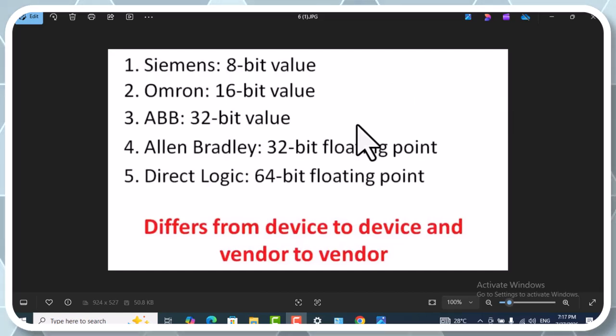And my friends, the OPC server solves this problem, which occurs when you read data from different PLCs or different protocol types. It reads the original device data through the correct industrial protocol, converts it to its own data format and applies it to the OPC protocol, and after that your OPC client can request this data.